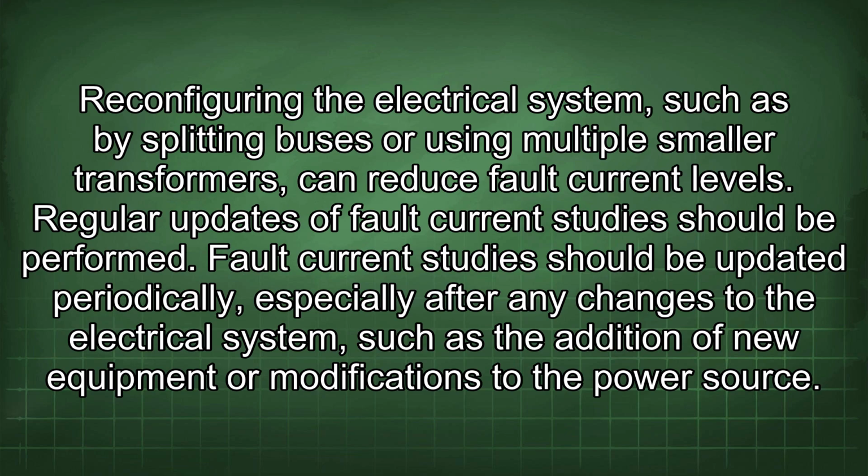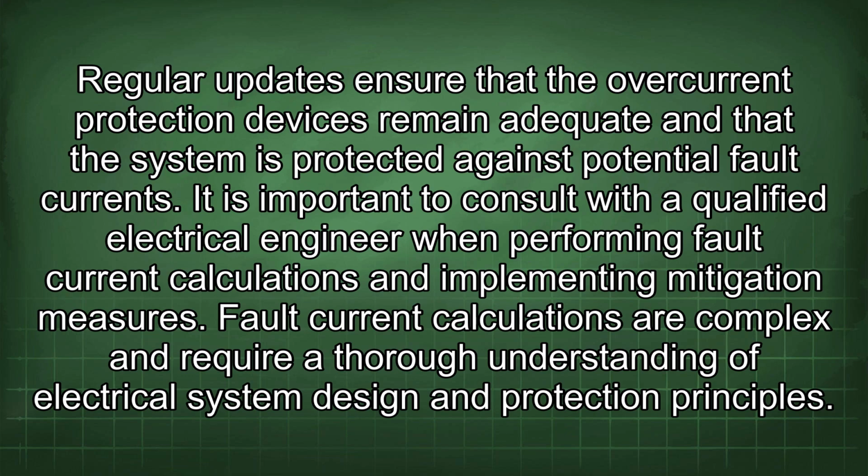Fault current studies should be updated periodically, especially after any changes to the electrical system, such as the addition of new equipment or modifications to the power source. Regular updates ensure that the overcurrent protection devices remain adequate and that the system is protected against potential fault currents.